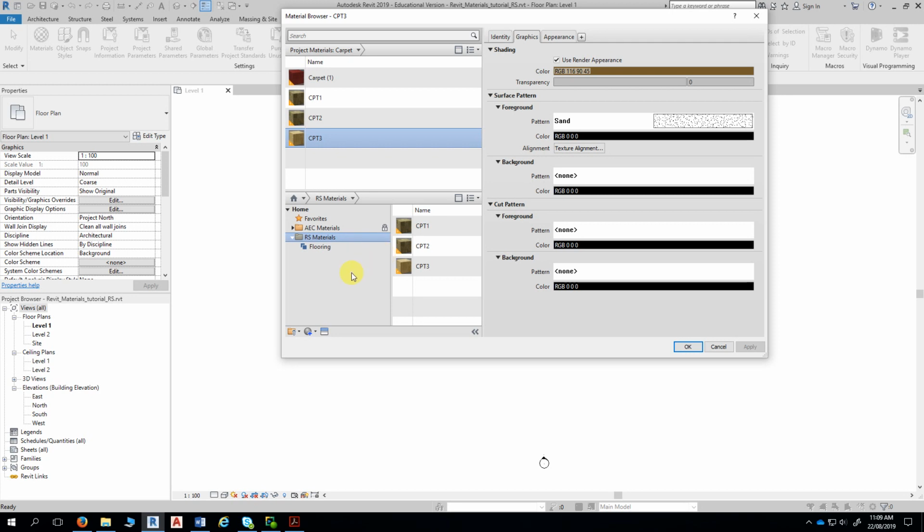That's all. Yeah, it's just to protect your confidentiality if you don't want anyone else to know. The thing is that in the classroom here, because the library itself is on a remote hard drive of your own, the mere fact of you ejecting the hard drive is going to remove it from Revit anyway. And even if you don't plug your hard drive back in for your next session and you open up Revit, it may be listed there, but it'll have a yellow triangle with a question mark in it because Revit can't find it if you haven't plugged your USB back in.